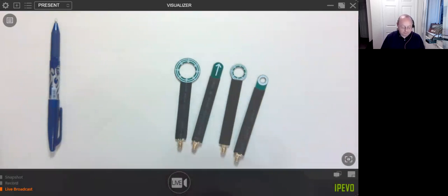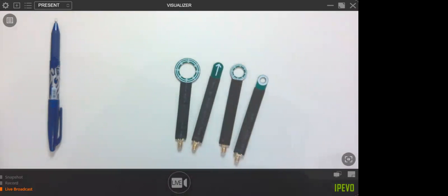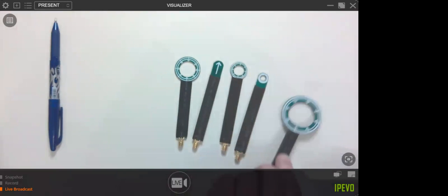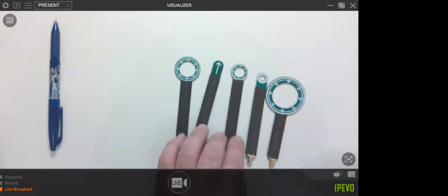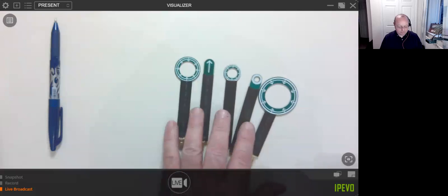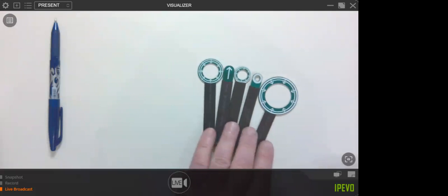And so next time, we're going to look at debugging. We'll cover a little bit on debugging radio problems, since it's been quite topical today, and some of the other things that I put into circuits to make my life easy for debugging. Can I just add the number one thing that I have discovered in the last month or so: give yourself a nice big fat ground pin, as in a real actual pin that you can attach your probes to and whatnot.